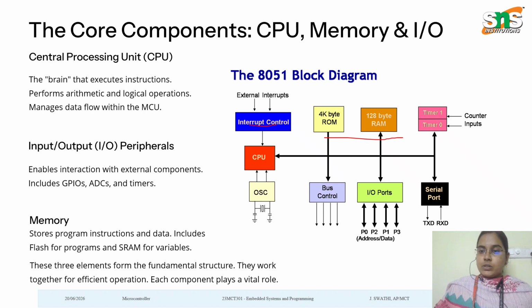And we have a timer circuit here, like timer 0 and 1, which we find in our pin configuration. And we have the input output pins. So the 4 ports may act as input output pins, whereas ports 0, 1, 2 may be used for address data enable, and port 3 can be used for your external interface.